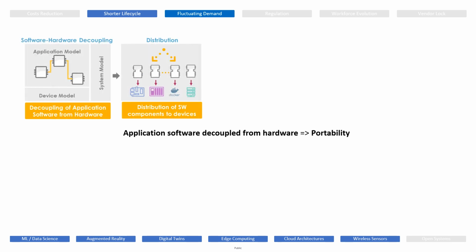In IEC 61499, the software is decoupled from hardware. This means the same control logic can run on different hardware platforms without modification, drastically reducing switching costs and eliminating vendor lock-in. This portability ensures that upgrading or switching hardware does not require complete rewrites, which saves time and resources.